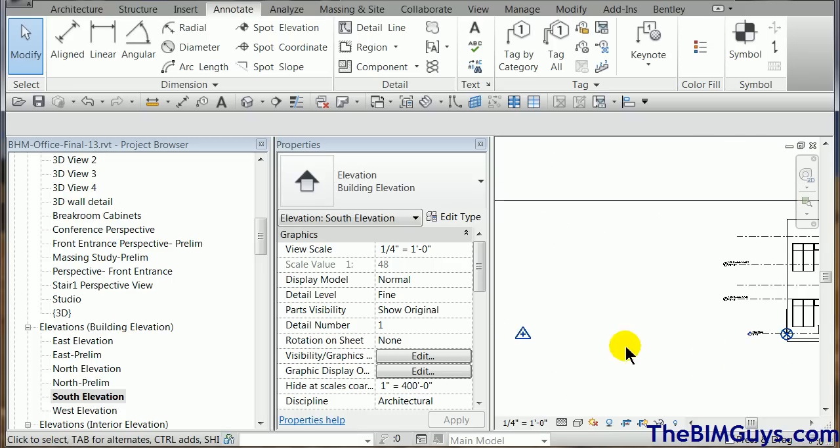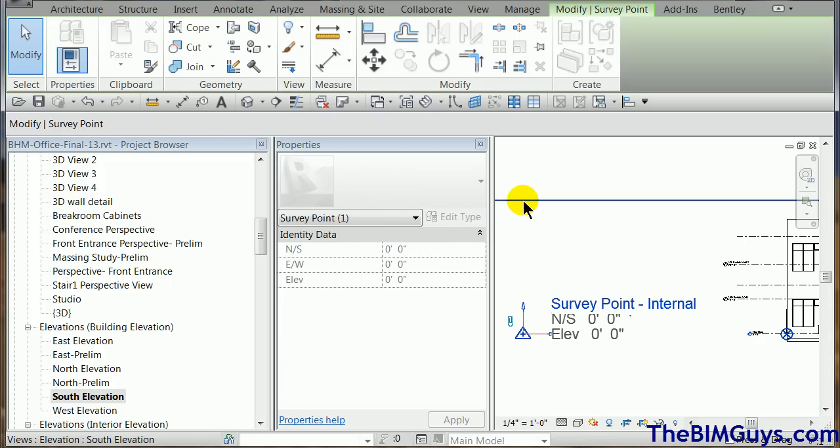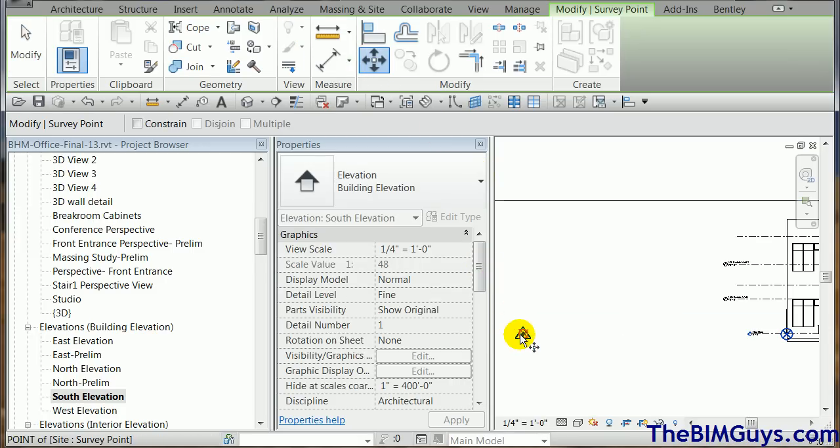And then way out here I have my site. Now remember the site, we don't uncheck it. So what I'd like you to do is let's take the site. Let's say it's about 12 feet down below our first floor. So I'm going to grab this element here. And again, I'm not going to unpin it. I'm just going to move it. Move. Pick a base point. I'll drag the direction I want to go. And maybe I'll put it at 12'3", just so it's something different, right?